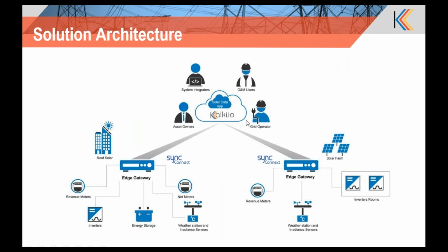Kalki.io can exchange data with utility systems like the EMS or the DERMS through standard telemetry interfaces. It supports utility standard interfaces like DNP3, IEC 60870-5-104 or 101. It also supports ICCP, that is Inter-Control Center Protocol. Usually we have integrated with the EMS systems using these three sets of protocols.